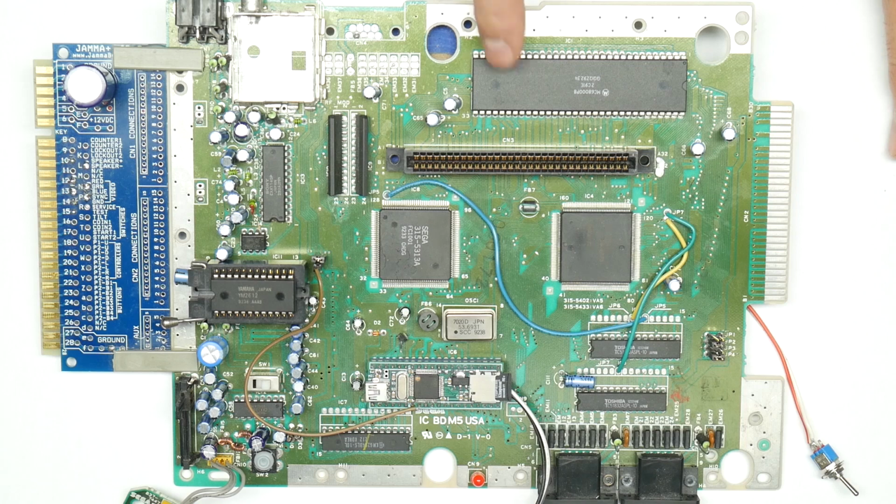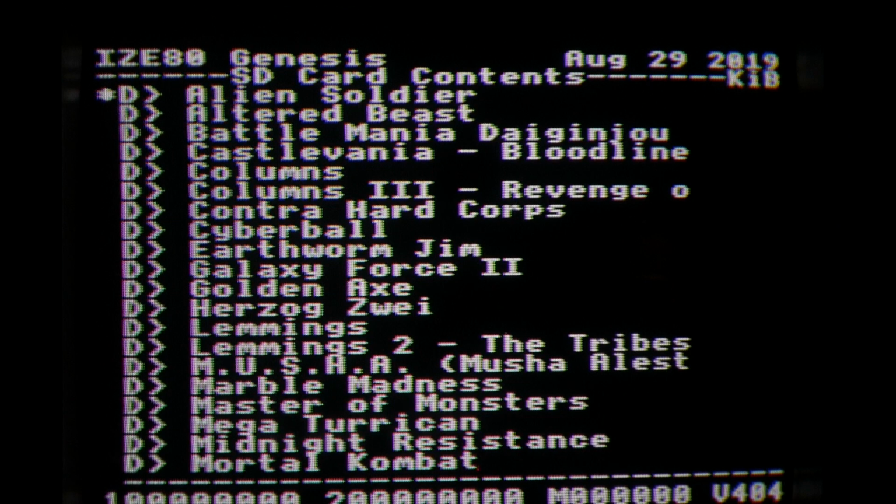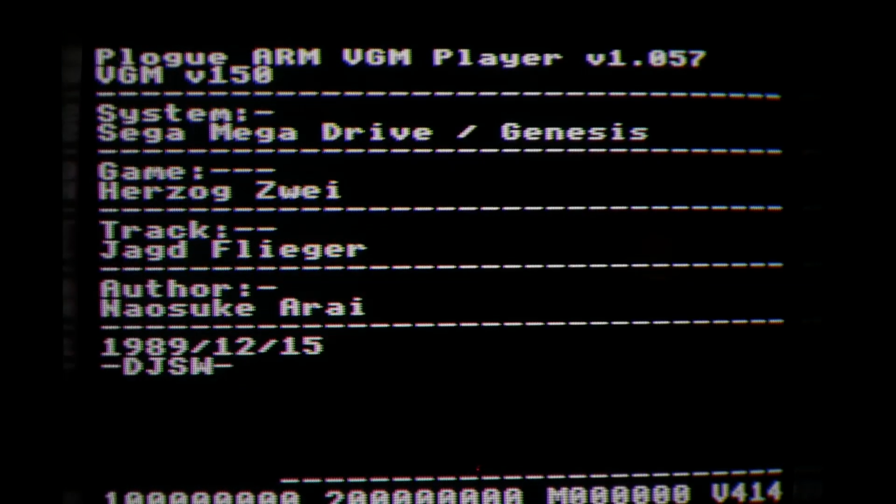With the 68K basically stuck in a permanent idle loop, I can drive the video in either Sega Master System or Genesis Mode 5 graphics and write to both sound chips. So I ported our VGM player to ARM, and I can play any VGM or VGZ file from the mini SD card. It's very nice to be able to compare complex mixes of sound, and for tests that use both the OPN2 and the SPSG.